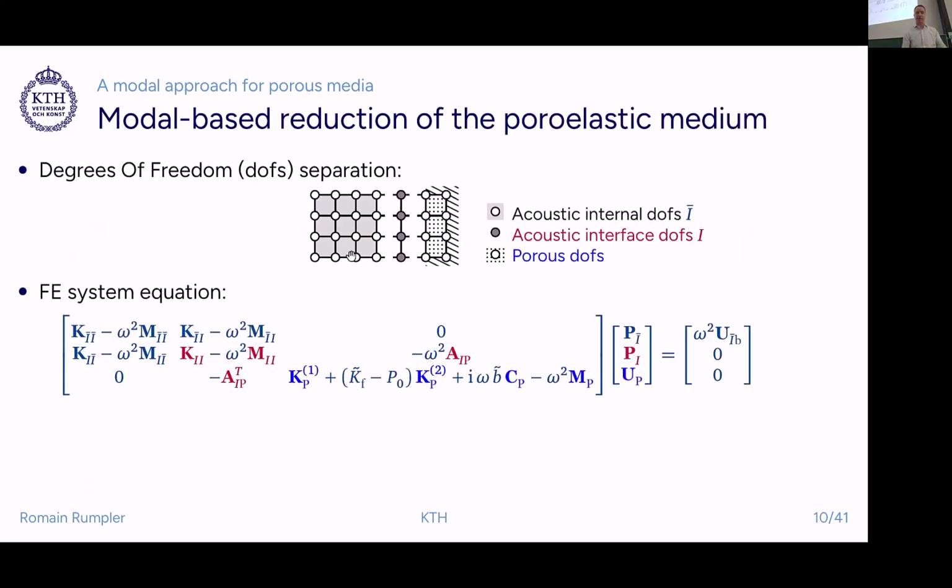problem for this. And for that, I will just use a component mode synthesis approach as Olivier has introduced, where you can disregard, really, we will never take care of reducing in this presentation, at least, the purely acoustic part. For practical reasons, we will separate it into interior acoustic degrees of freedom in the acoustic cavity, and then degrees of freedom at the boundary of the acoustic cavity, purely for the sake of using a modal approach for the poroelastic degrees of freedom.